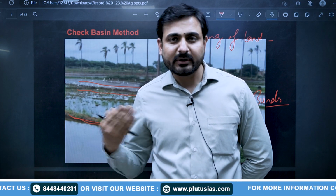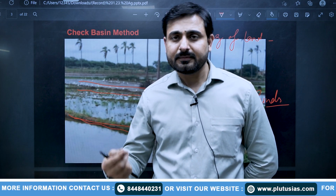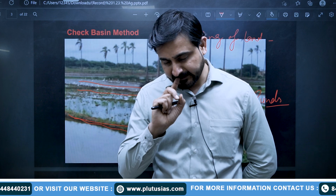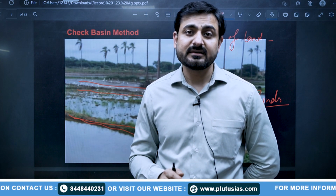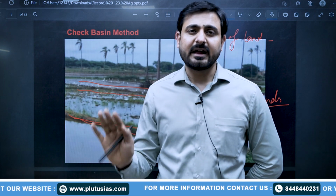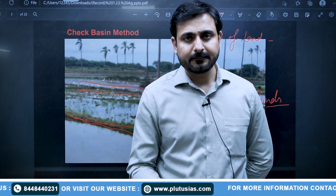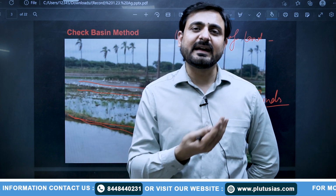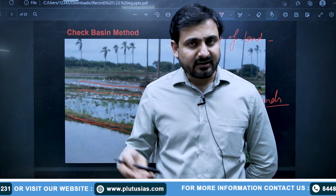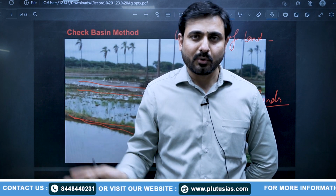So you can say here soil runoff and soil erosion can be reduced. The soil runoff and leaching of various nutrients inside surface irrigation is very high, but inside check basins generally very low. Further, during heavy rainfall, check basins, especially these bunds, help control the water. Means there is no uncontrolled flooding. There are very high chances during heavy rainfall that water, along with various essential nutrients, moves away. Yeah, soil runoff takes place. The very rich topmost soil generally moves away with the water from the field.